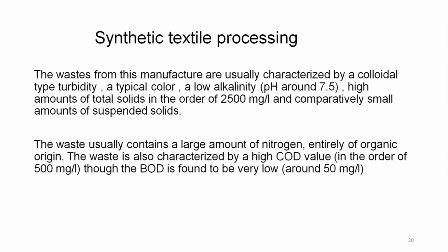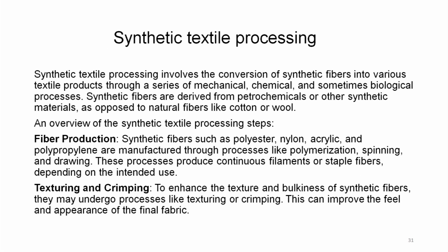The waste is also characterized by a high COD value, in the order of 500 milligram per liter, though the BOD is found to be very low, around 50 milligram per liter. So, you see that if we compare synthetic fiber with natural fiber, these parameters are quite different, that is the COD, the BOD and the total solid content.